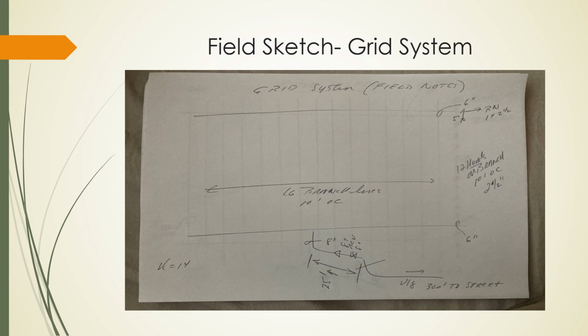However, if there are 4 or more outrigger heads, then I'm kind of scratching my head as to why someone did something like that, and now I've got to include that design as well because it may come into play. I really shouldn't have that number, but I suppose there could be circumstances. I just did not run into that. Usually there were a minimal number of outrigger sprinkler heads, those heads outside the grid system. So I leave the loop system to you to try to figure that out.